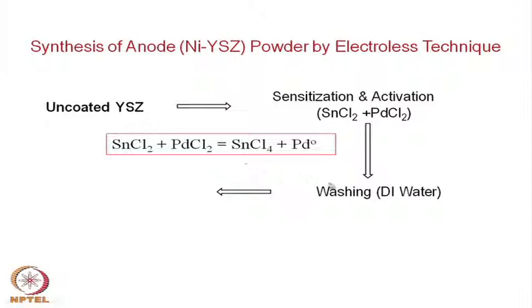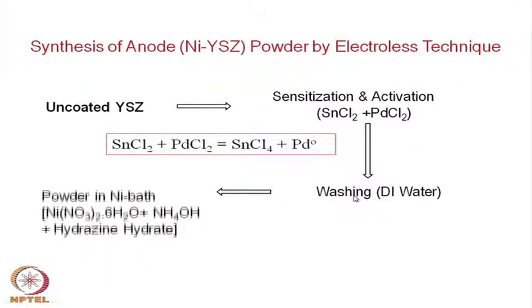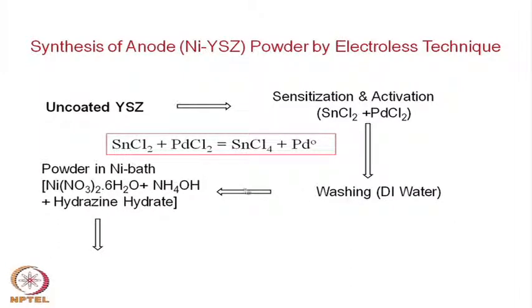Then of course, it is washed with deionized water, and finally these sensitized powders, that means palladium coated powders, are put in a nickel solution bath, containing nickel nitrate, ammonium nitrate, and some reducing agent like hydrazine hydrate.